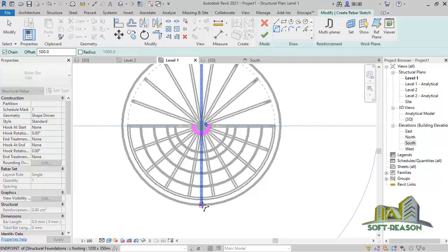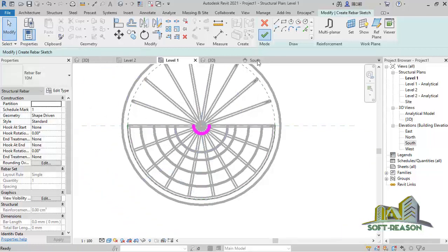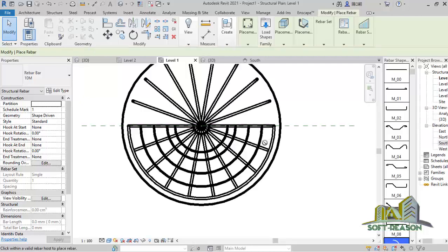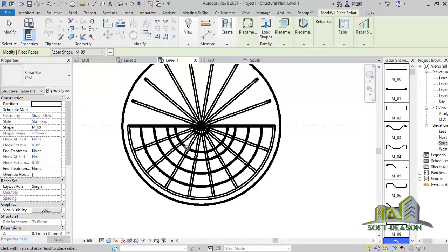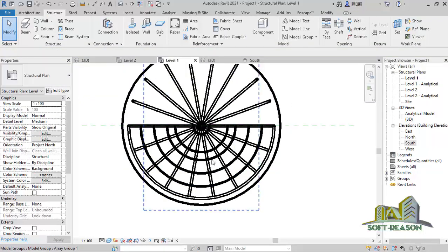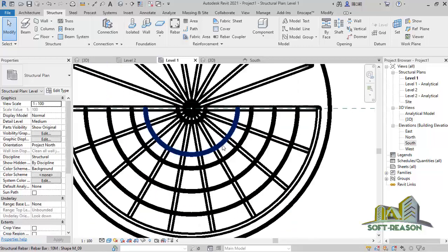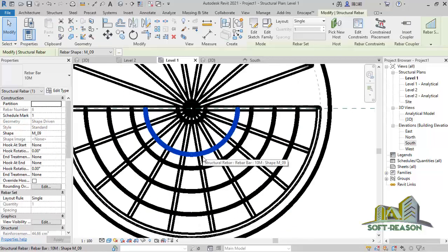So I can see the spaces there. The spaces there are too much. So I will click that, of course. Then after which, deselect the command, click on finish edit mode to have that rebar. So I want to deselect the command, select this particular rebar, this one, and then I want to be deleting this one at first.